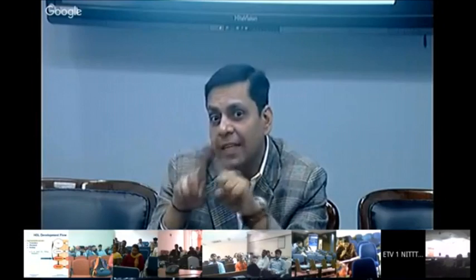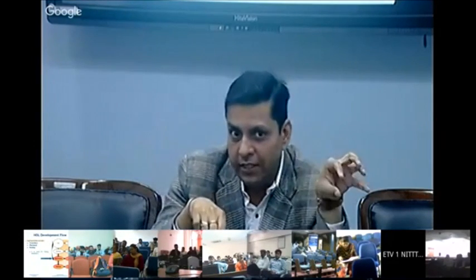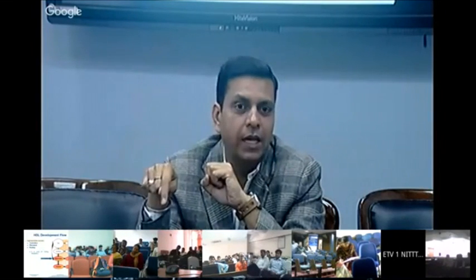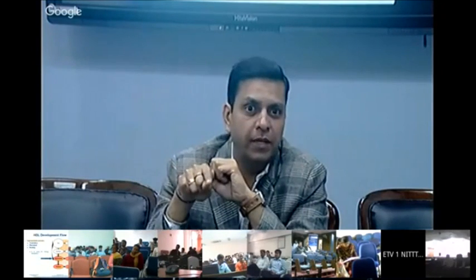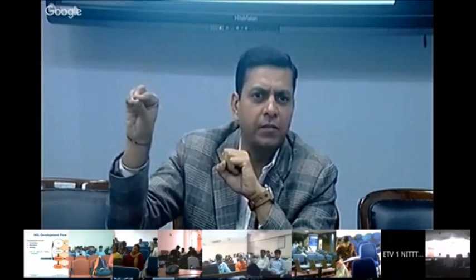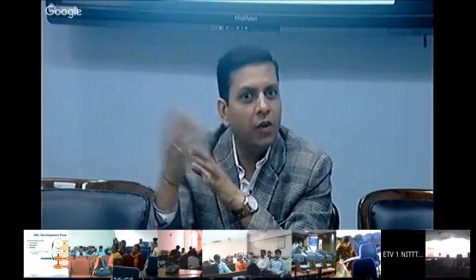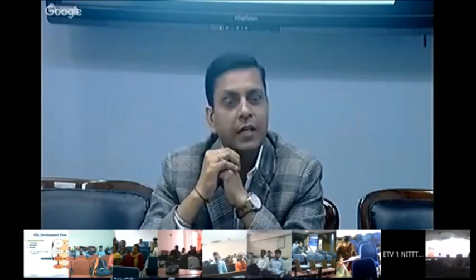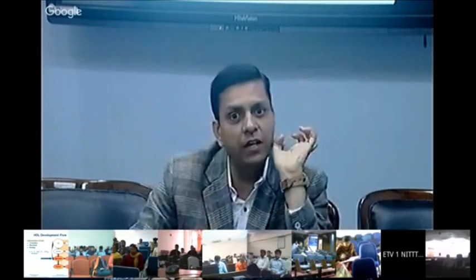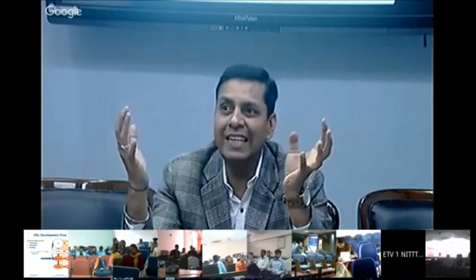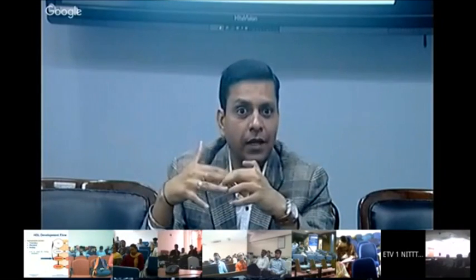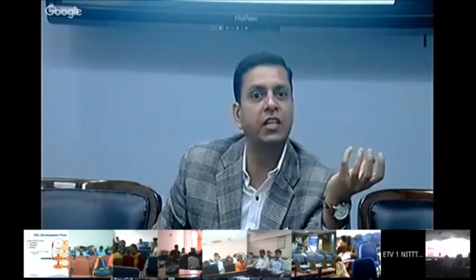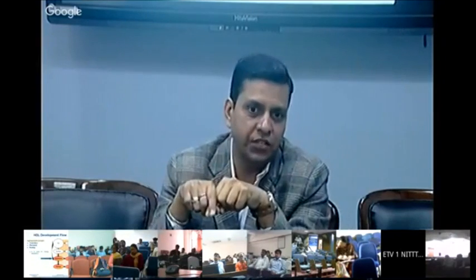So translation here means identifying the required component in your design and selecting, from the existing components available in the library, the one which is optimal for implementation. So out of those 20, let us say number 7 is more optimal as compared to others. So I am going to use that number 7 full adder for implementation of my design. So number 7 will be used for this particular full adder. This is basically what you can also call library binding. We are binding different components in the library with our existing required components. So this is known as your translation, right?